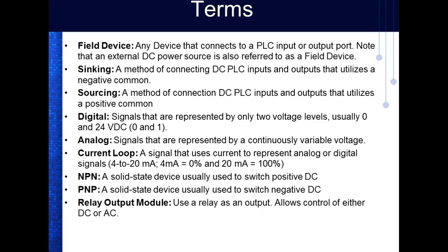Well, the problem is I'm using that feedback to control the speed of the motor, and I've got to run that feedback from my sensor out there through copper wire. Right? You understand? And if it goes through a noisy environment and I don't spend a lot of money on my cables, then it's going to screw up all of my sensor readings and stuff like that. Well, the problem is that this does not really generate a lot of current, but it generates a voltage. So that means if I can use a current as the signal, then it means these 4 to 20 milliamp are basically noise immune.